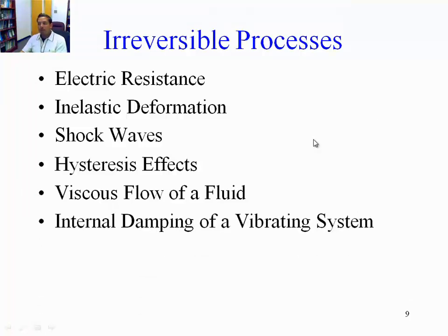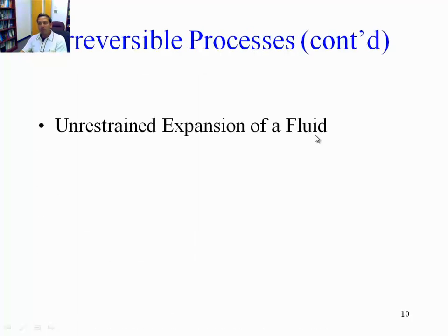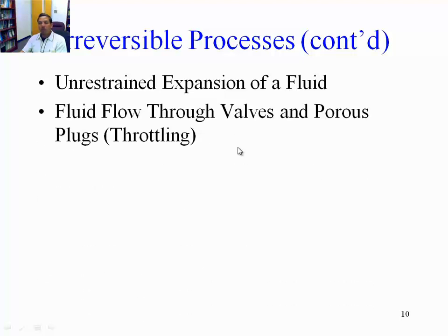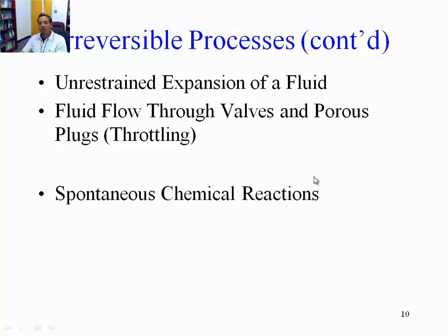Internal damping of a vibrating system, for example, is also an irreversible process. It leads to dissipation. Solid-solid friction, more irreversible process. The unrestrained expansion of a fluid. Fluid flow through valves and porous plugs or porous media. That is a typical example also of a process that cannot be reversed.